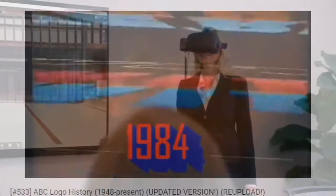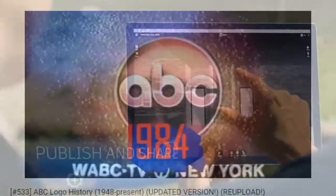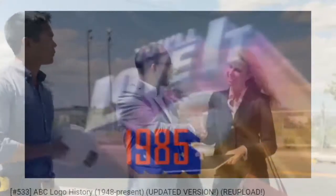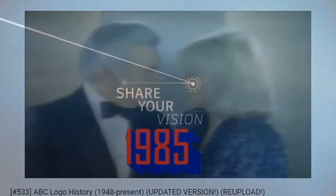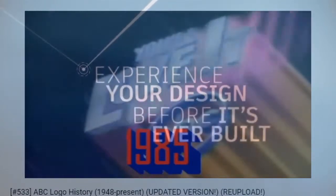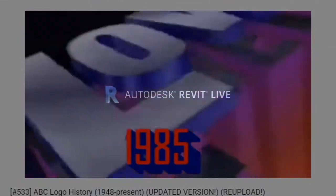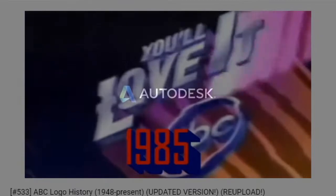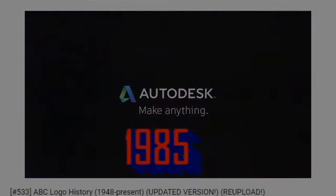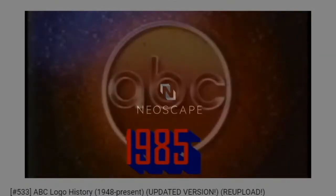In the Material Browser, type Carpet in the Filter search. Return to the Modify tab in the ribbon. Select the Paint tool in the Geometry panel, just below the Split Face tool. In the Material Browser, type Carpet in the Filter search at the top. Now we have a few. Okay, so this will minimize your choices, allowing you to select carpet tile from the filtered list.